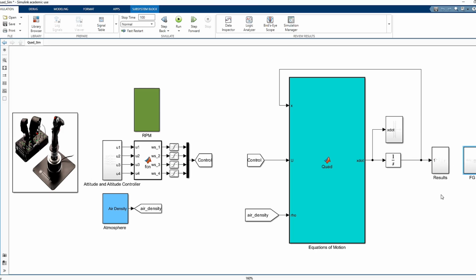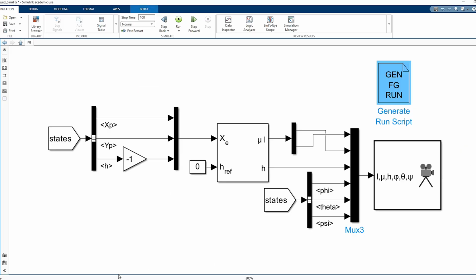Okay. Before this, you can observe here, if you have a position x, y, z or h and angles, roll angle, pitch angle and yaw angle, phi theta psi, then actually you can say how my model is behaving in 3D space, right? In a similar way, we will send x, y, z data and phi theta psi data to FlightGear, and to connect FlightGear, we have a pre-configured 6DOF animation model.